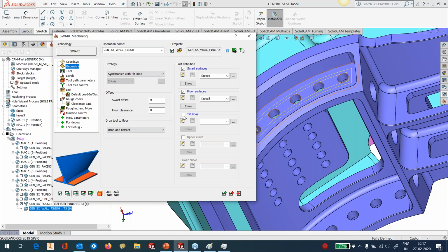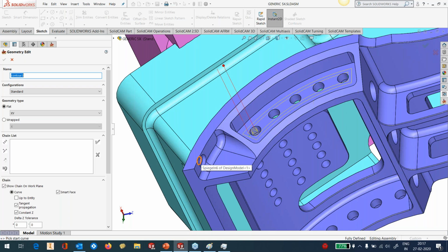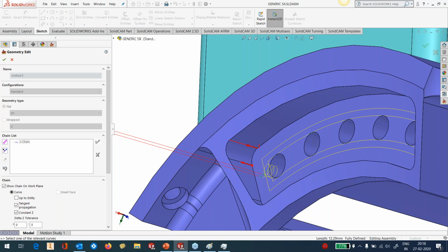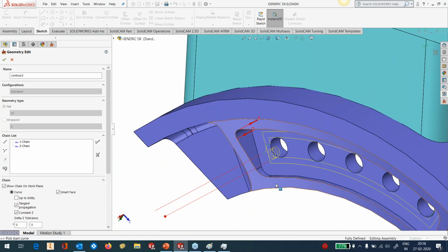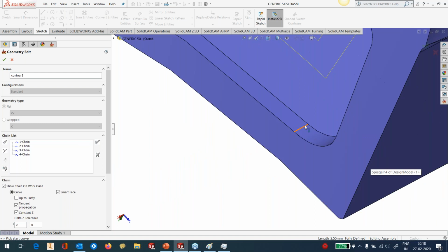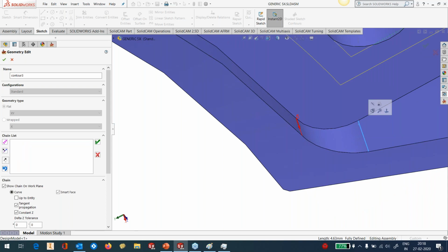I'm also going to use tilt lines because I want to control the tool axis. I don't want the tool to dance in areas because some of the surfaces are not great because they have different ISO lines, they have different widths. That's the reason I would like to define tilt lines, simple tilt lines, 8 of them. So just pick 2, so the third, okay, fourth, then after the fifth one, sixth one.